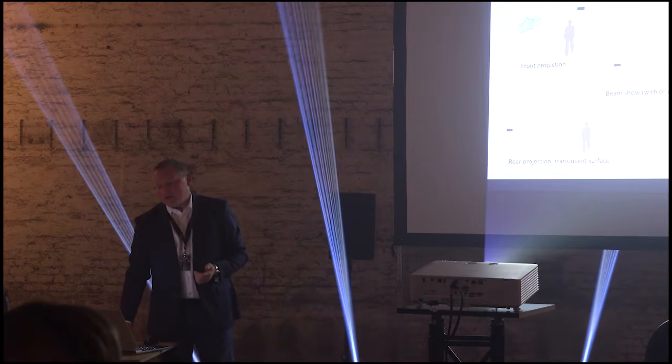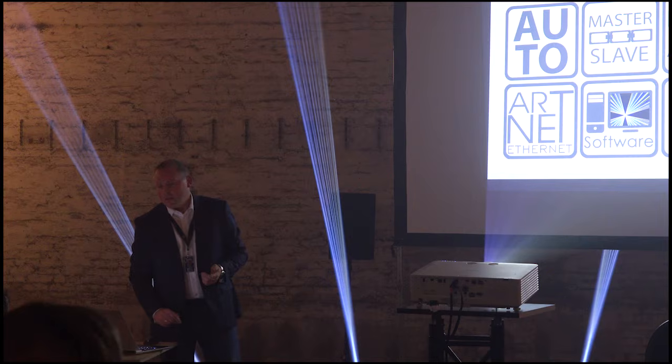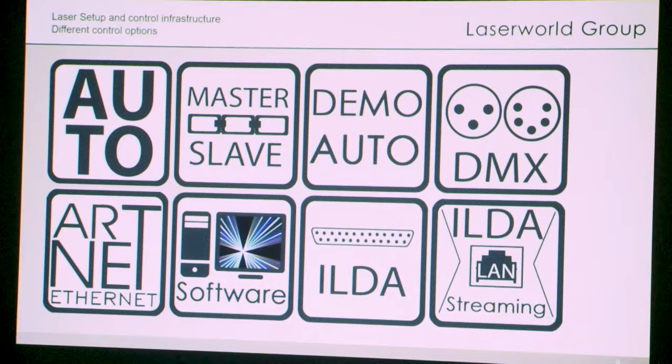The next question always is, what about control? What control options are required by the customer and by the project? That is a crucial thing. Many people don't think about that when buying a laser. They say, I want to have a laser. But yeah, how do you want to control it? If there is a lighting designer coming in who wants to control the laser, well, they have their control systems. They have their DMX controller, ArtNet. They want to use this for control, and they probably are not too fond of having additional software.